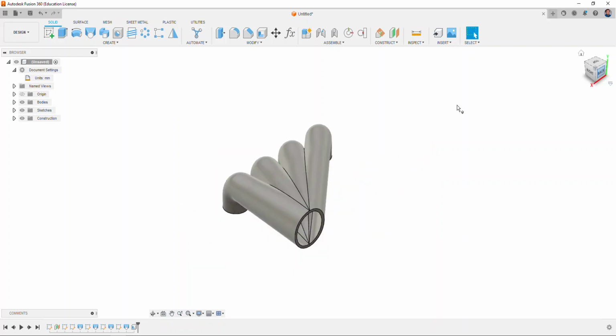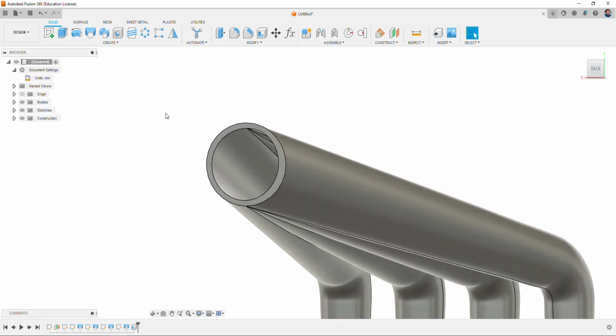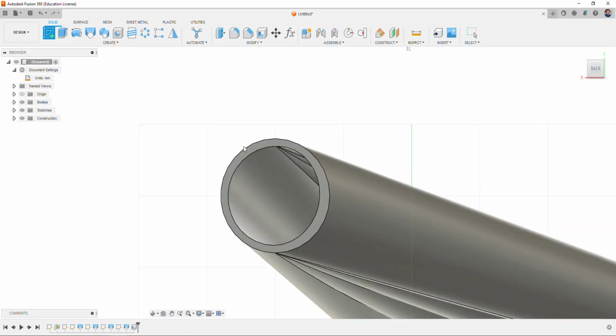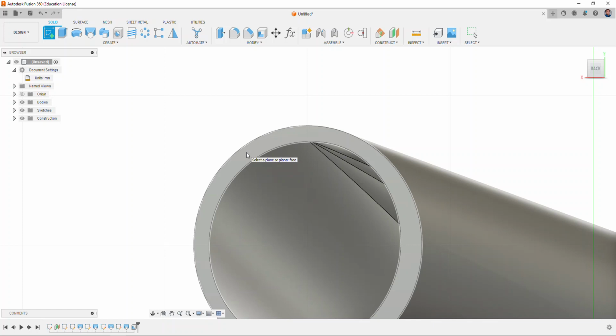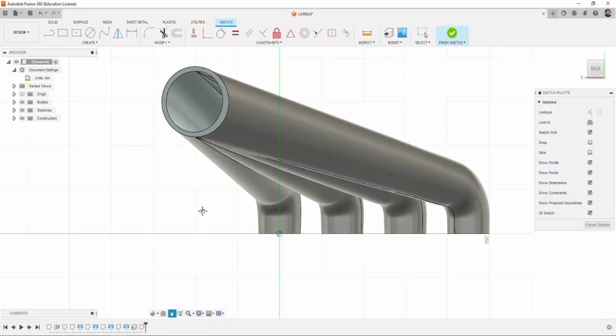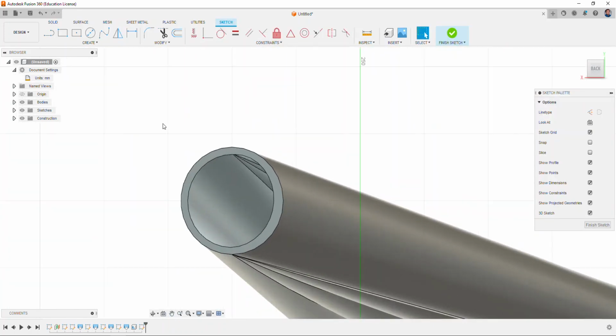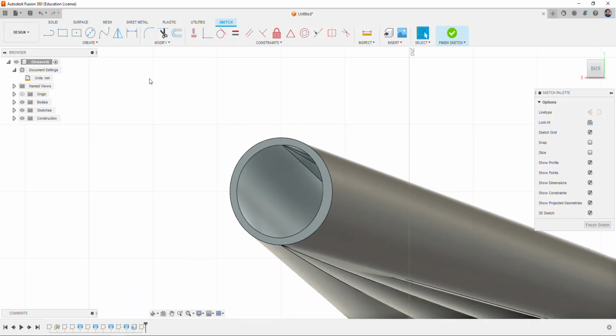I'm going to turn this to the back and create a new sketch. I usually try to pick between the circular ends there. We're going to create the bracket where it goes through and gets attached as it goes along. So I'm going to choose the line command. As I hover over a circle, you can see a light blue circle that can be done here. I'm going to draw out and go to the end. You can see that triad shows up. I'm going to uncheck that, and then I can right click and say OK.